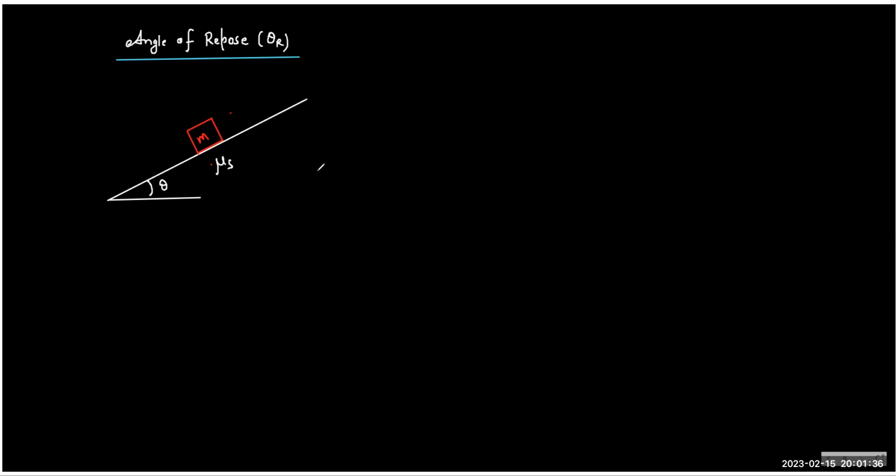And the coefficient of friction will predetermine that motion. It has nothing to do with the mass of the object. So whether we have an elephant or a mouse, if they are wearing shoes of the same company with similar features, standing on the same plane, both will start skidding only at the same angle. So mass doesn't decide the repose angle. That's very interesting.